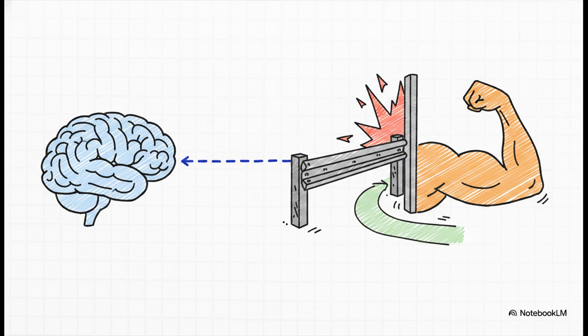But, of course, every smart system needs safety guardrails, right? In this closed-loop process, there's a really strict component called a limiter. This limiter is constantly watching that slip command we just talked about. Its whole job is to ensure the controller never accidentally commands a slip speed that pushes the motor past its maximum allowable torque threshold. Basically, it acts as a safeguard to prevent the system's brain from ever asking the motor's muscle to do something physically impossible.